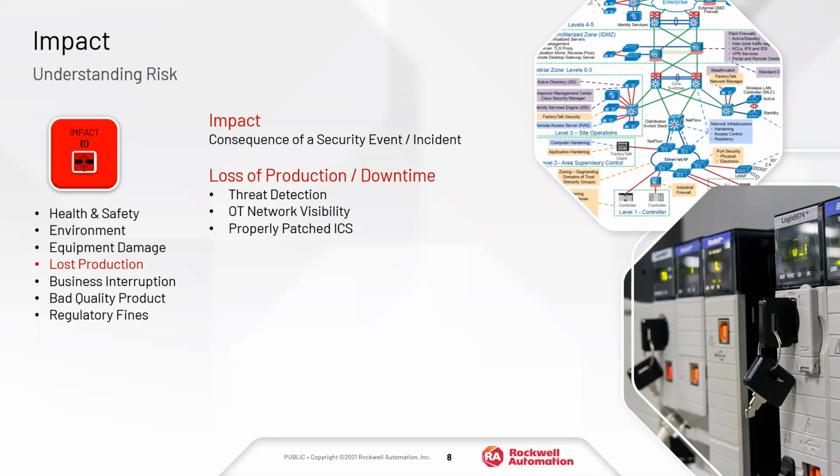So having the control system health checks in place, Windows operating system patching, vendor level patch validation. From the Rockwell perspective, we provide a knowledge base that has the Windows updates and verification of what's been tested with Rockwell. We also have the FactoryTalk system level patches.